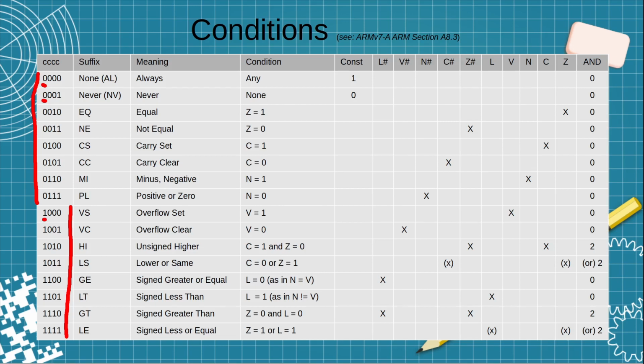But then I started thinking and I started to realize that these are actually built out in pairs. And it's not necessarily that I need to have the inverted signal. What I need to be able to do is just invert the condition when it's been selected. So rethinking this, if I was to take these 3 bits to select on the 74HC151 and then this least significant bit then would determine inversion, whether I invert a signal or not, that could save me quite a bit.